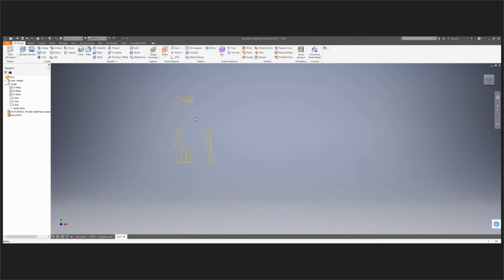Now, we can do something else. Let's crop this view a bit. Let me zoom in. You know, I have this front view, side view, top view. I don't need all those. I just want to keep this one. So what I'm going to do, I'm going to right-click again on my node and say crop. Now, crop is pretty interesting because I window select what I want to keep, like this. Right-click. Okay. Boom. Everything else is gone. I just have the view that I needed. Now, this is awesome.